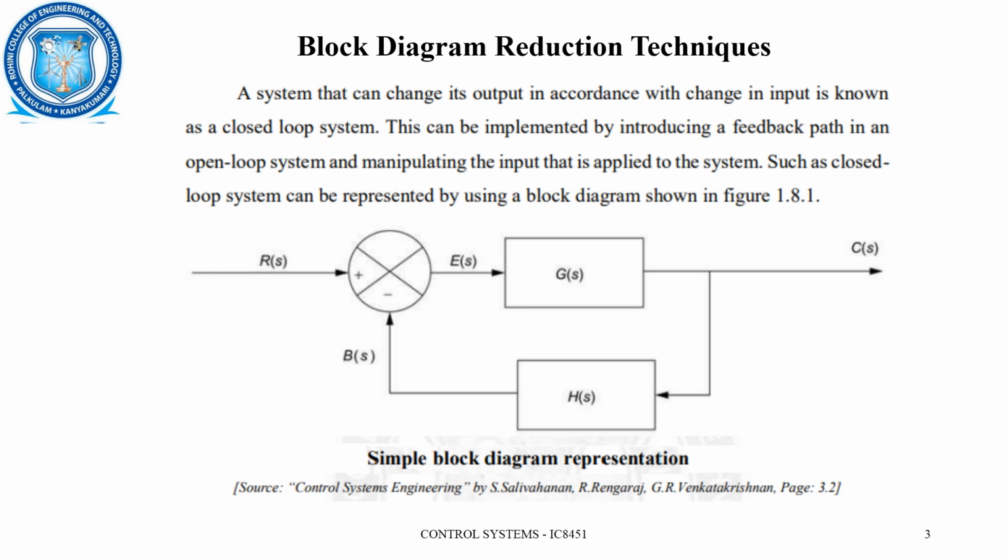From C of s, a sample is being taken and fed to the feedback element H of s. This will produce a feedback output B of s. So in this way, here we have used one summing point, two blocks, and here it is a node. From this node we have taken that value.